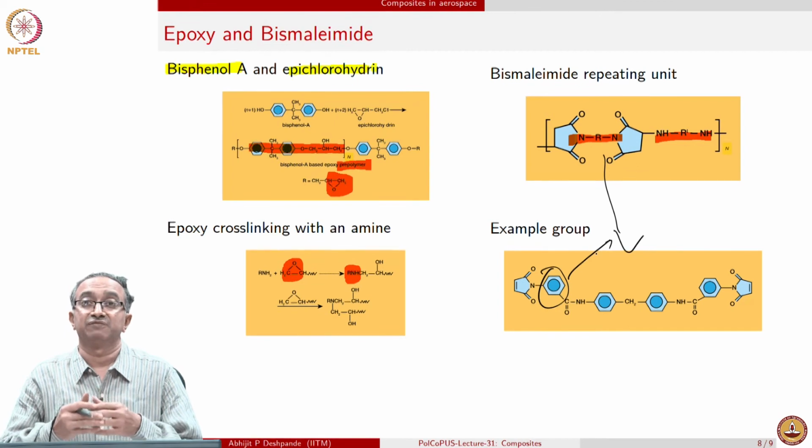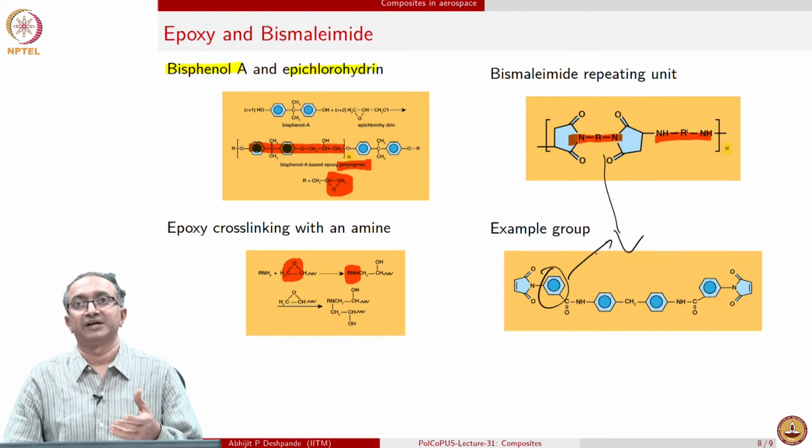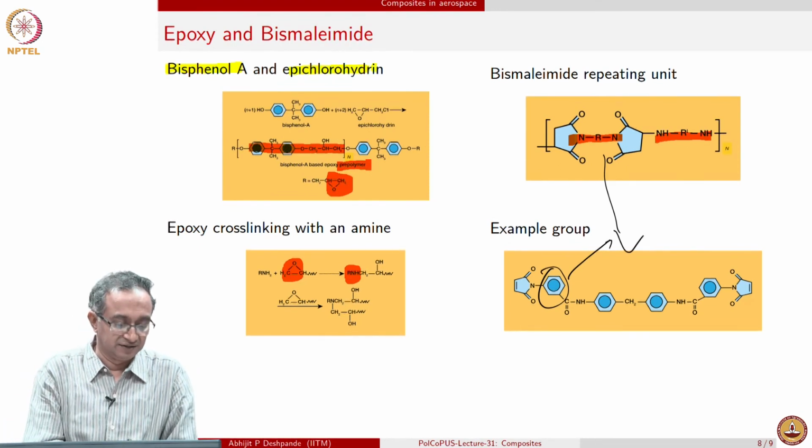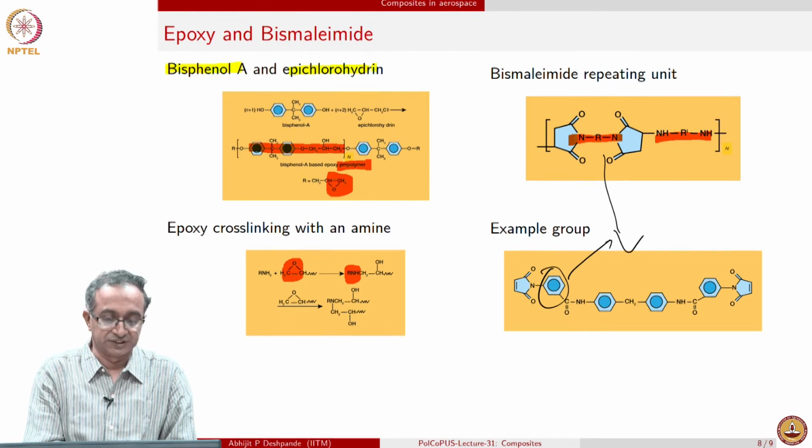So, you have to go to progressively higher temperature to obtain segmental flexibility in these materials, and that is what we are trying to exploit when we use them in aerospace applications. There are several parts in the aircraft which can see temperatures of 120, 130, 140 degrees Celsius, and by using these composites with these neat matrix materials, we can easily sustain the overall structure.